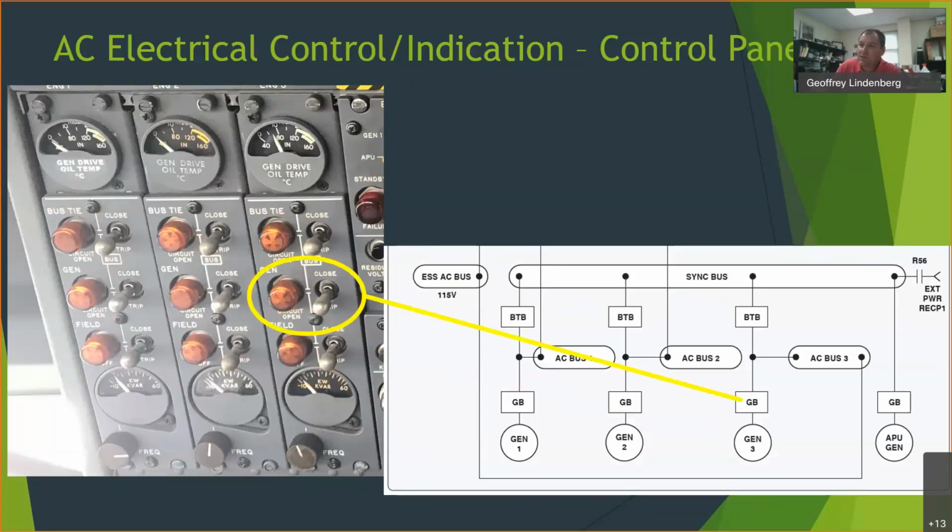And then once it's producing electricity, you have to get the frequency in phase. And here is that frequency knob I was talking about. The lights to do this are actually just right here. Here's one of the blinker lights. There's another one about right here. Those are the syncing lights. This is the panel that you kind of just see as the sync panel.